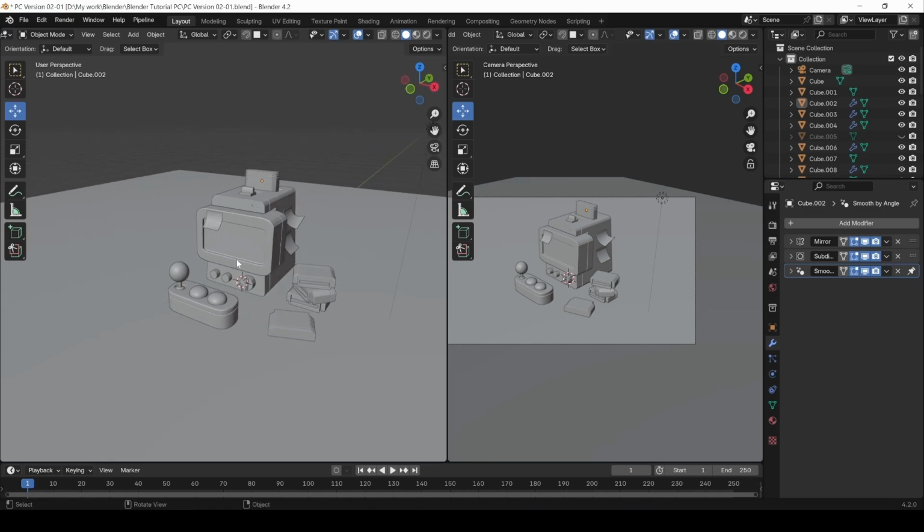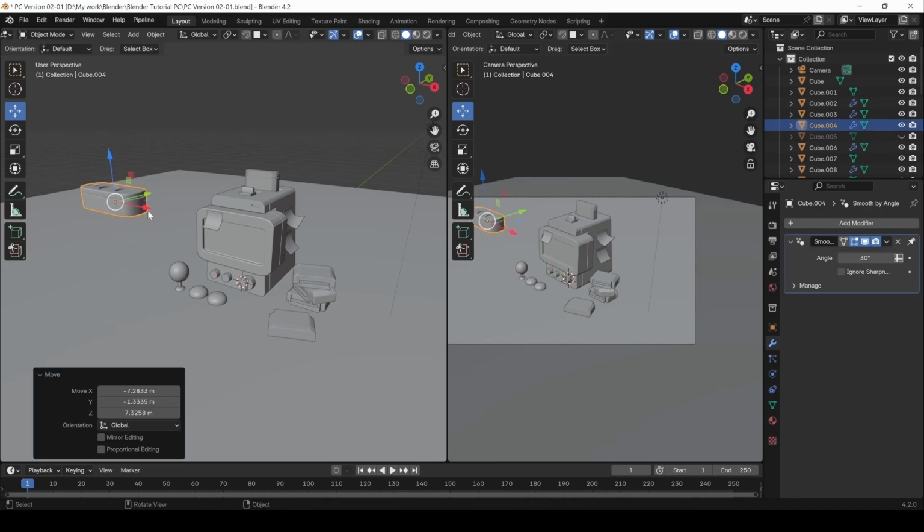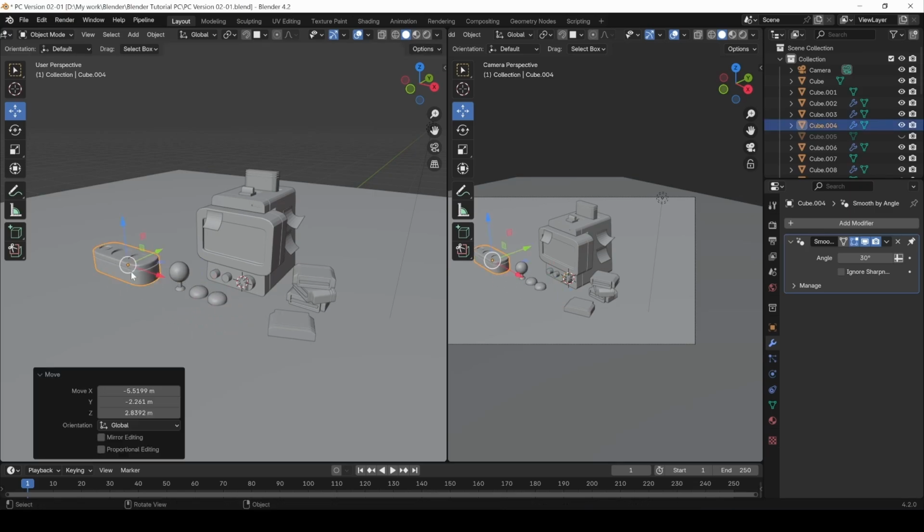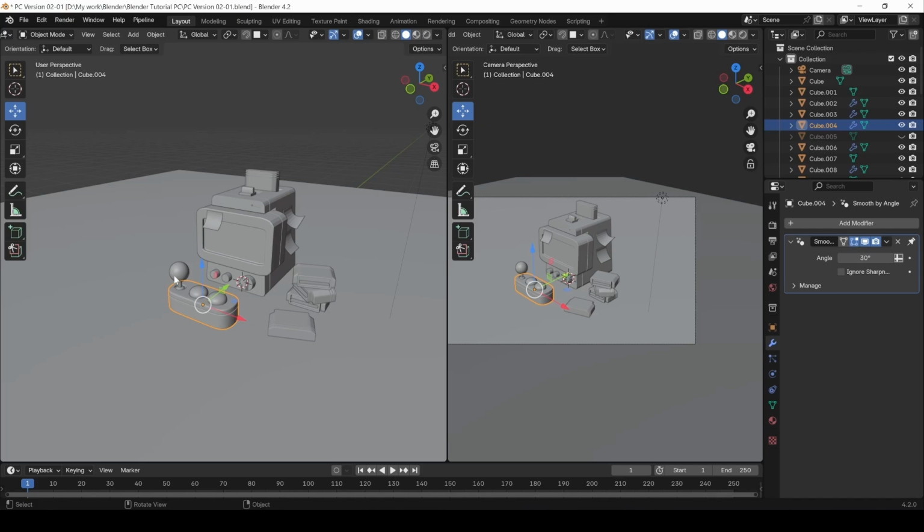One last thing I remembered I did not talk about too. I know there is a lot of things I'm talking about, but this is pretty important actually. So if you move this object, it moves alone. It does not move with this because they are not the same object. But what if I don't want them to be the same object, but at the same time I want when I move this, everything will move with it. So to do that, it's actually a parent-child system where when the parent moves, the children move, and this is what we need to do.